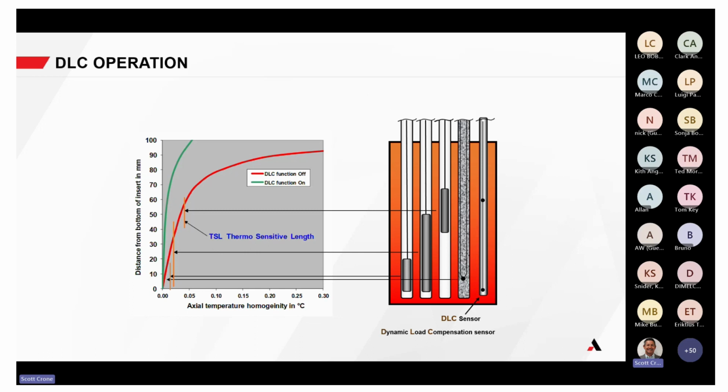So those 3 different sensors in the well have different depths where the sensing elements are, and there's a slight change, and it's up to 5 thousandths of a degree between the one at the lower and the one in the upper. And that's based on the axial gradient going from bottom up to about 60 mils in the range. If you look at the green curve, there's virtually no change between those 2 up to that level. And it controls that heat energy to maintain it that way.